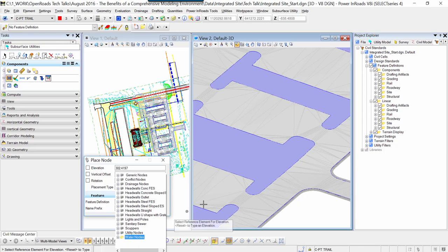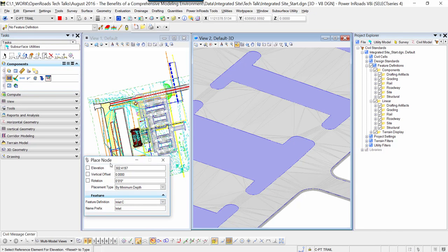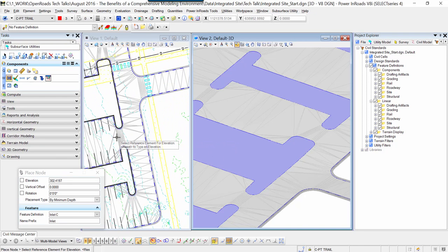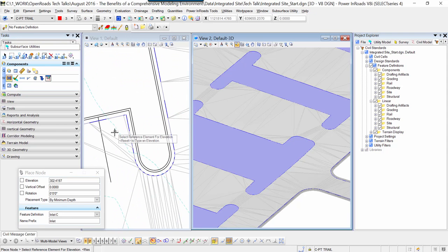So recognize here that the terrain for this parking lot was constructed. Now I'm coming in, or this could have been referenced in to the drainage engineer, and they can come along now and place some inlets and a drainage network across the parking lot. So let's just do that. I'm using the drainage tools within OpenRoads at this moment, and let's just say here's a low point. I'm going to place this inlet. Okay, I'm just data pointing through the prompts.